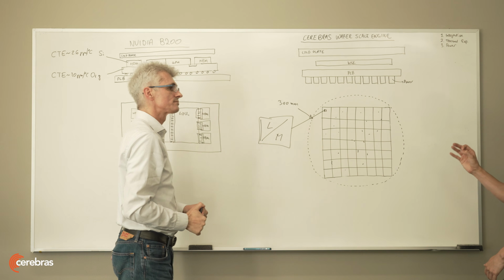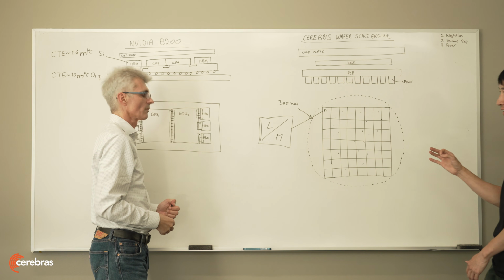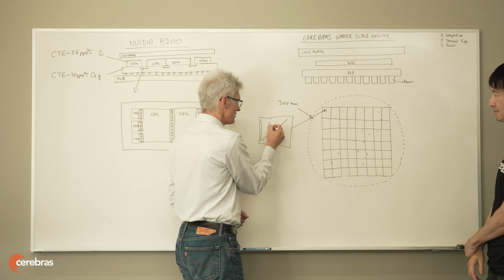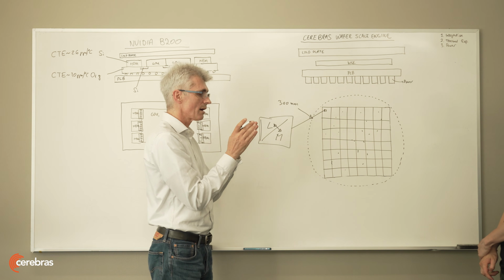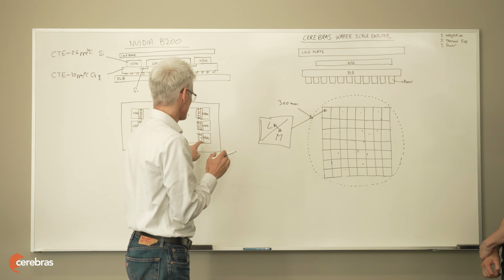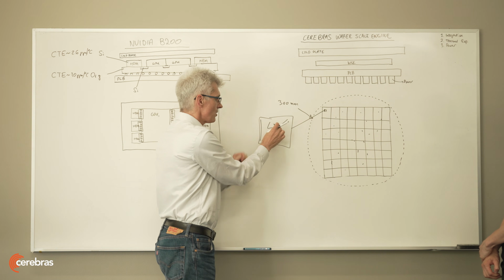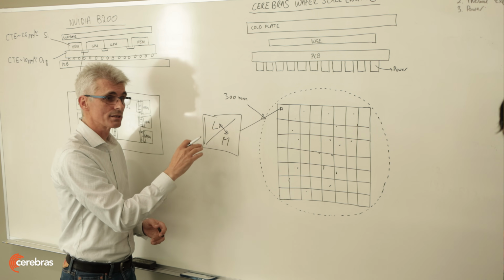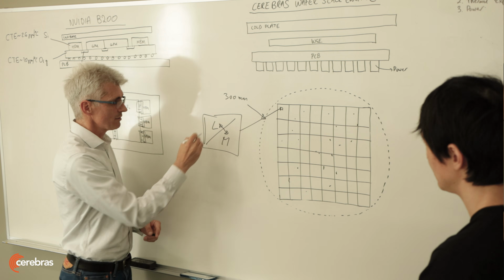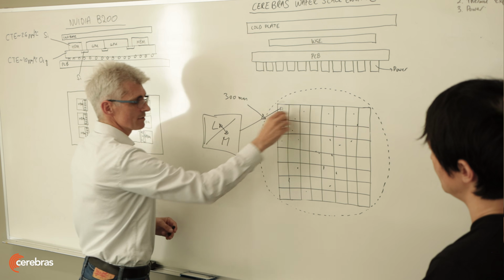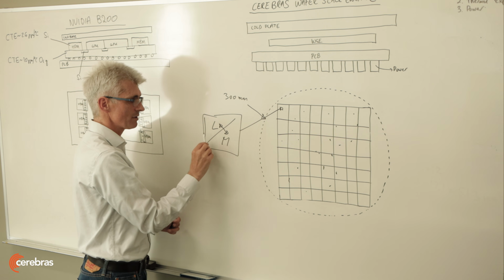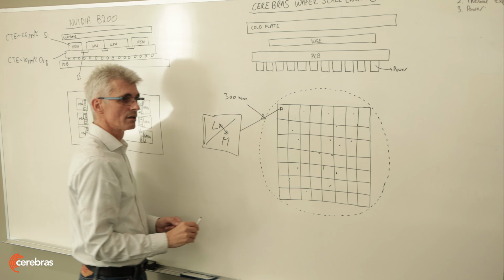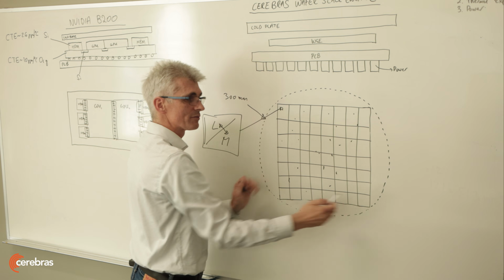This solves the memory bandwidth wall that has plagued the whole microprocessor industry for decades. These two pieces being so close to each other allows you to have very, very short wires, much shorter than what you have here, with a very small amount of capacitance, and therefore very low energy requirements to communicate. Also, you distribute the memory over a larger surface, which allows you to better serve the various cores within a given reticle or large piece of silicon.